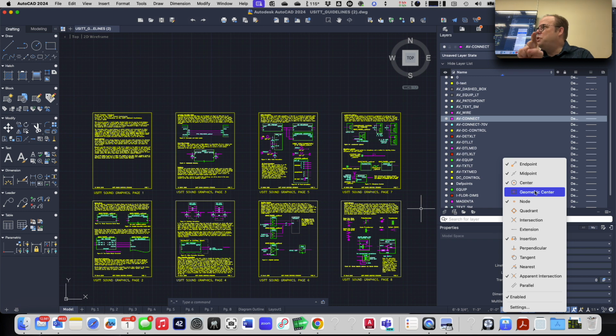You know for sure that when you hit click, you clicked on an exact spot, that you know definitely it was that spot and not like 0.0035 on the X next to it, right? Object Snap will force you to click exactly on the line, which is super helpful.